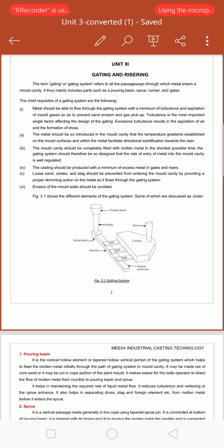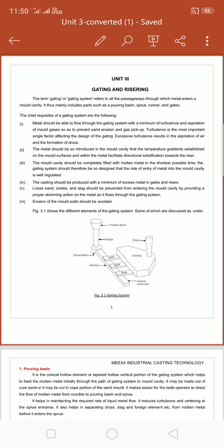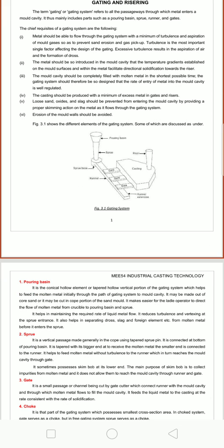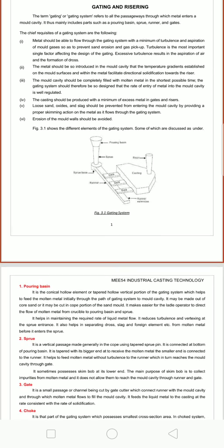It may increase the velocity of the molten metal because of the smaller cross section area at the bottom. Therefore a straight or cylindrical sprue would not be used at the bottom, since a low pressure area is created around the metal in the sprue. Then the sprue base, or sprue well, or sprue bottom, as they call it, is a wider cross section at the bottom of the sprue to reduce the momentum of the molten metal. As the molten metal moves down the sprue it gains velocity, some of which is lost in the sprue base, by which mold erosion is reduced.